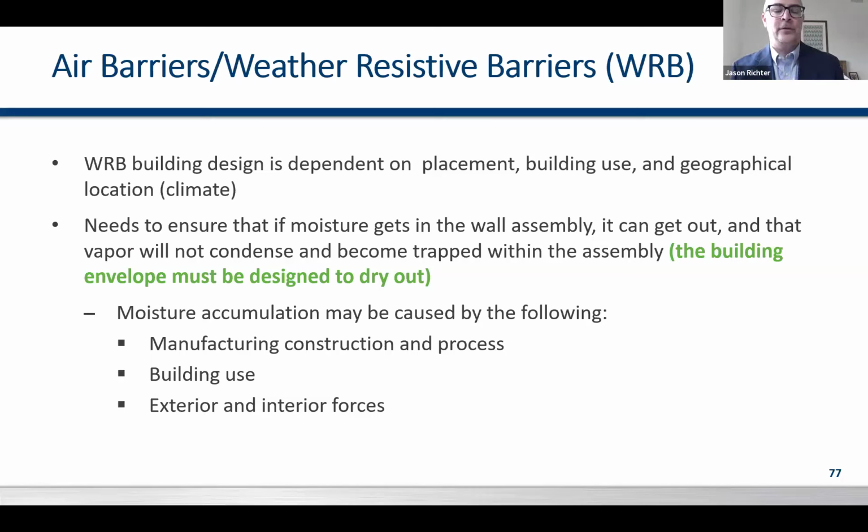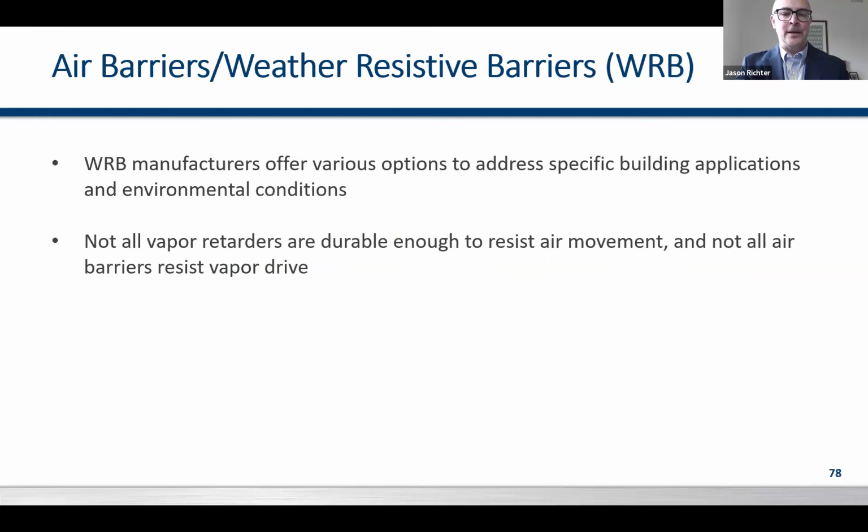So again, we're looking to create more holistically healthy building environments for our occupants today. Weather resistant barriers, building design is dependent on the placement, building use, and geographical location. Like I said, somewhere on that ASHRAE map around zone 3, zone 4, you're going to flip where that is in your wall assembly due to the high degree of humidity present and the higher temperatures in those environments.